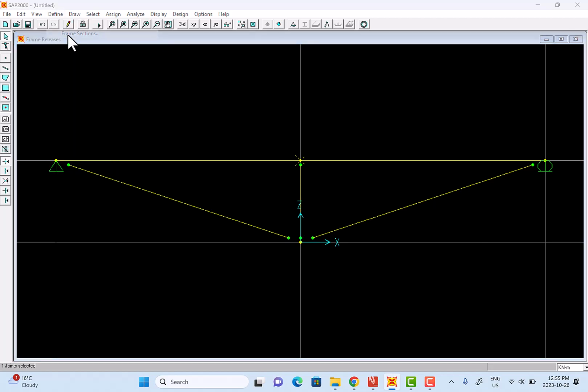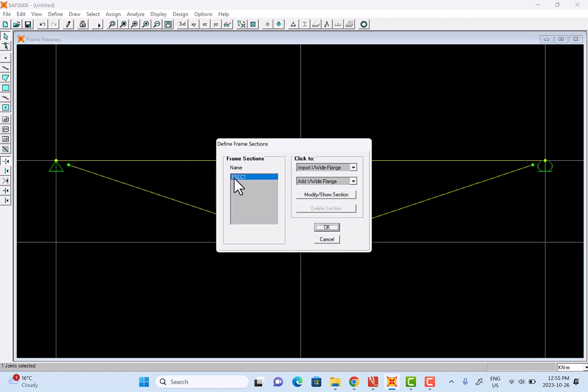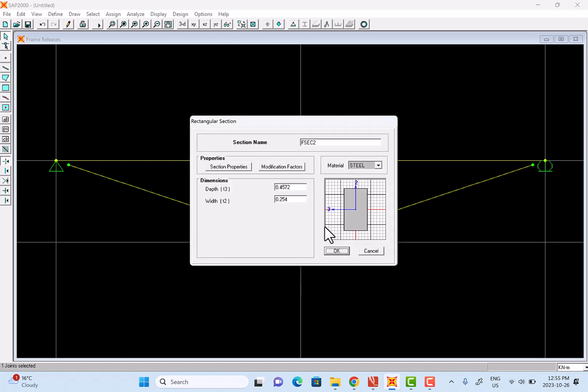So I'm going to open this up, click on that, and there's obviously this default one, but what I'm going to do is add, well, for the timber beam, I'm going to add a rectangle. So there we go. Let me call this the beam. And I want to switch out the material to this new timber that I defined. And here's our cross section.